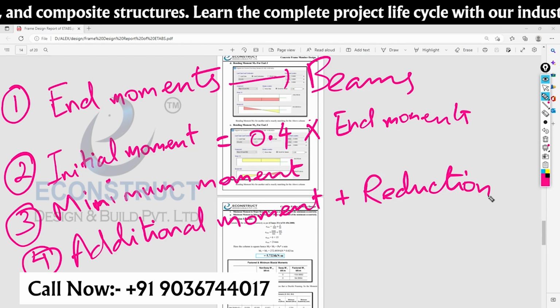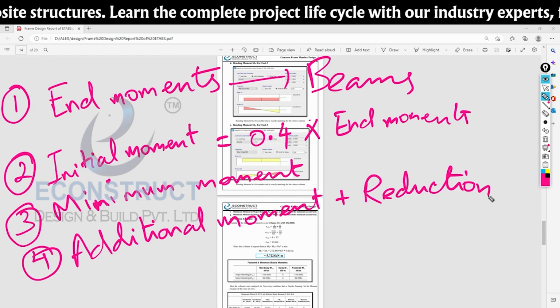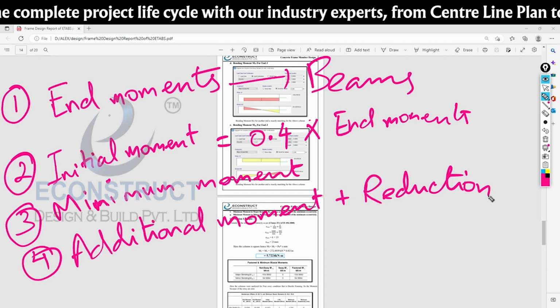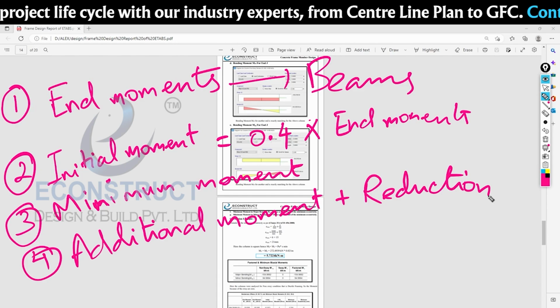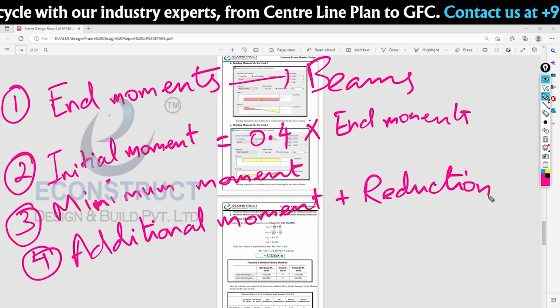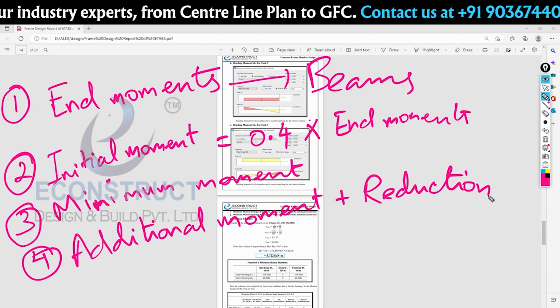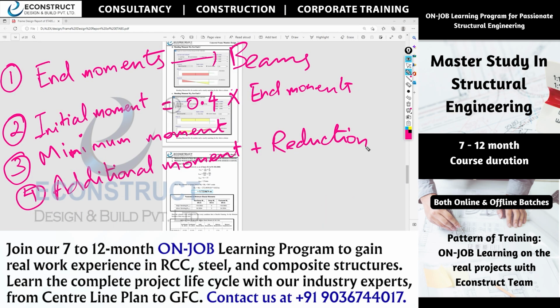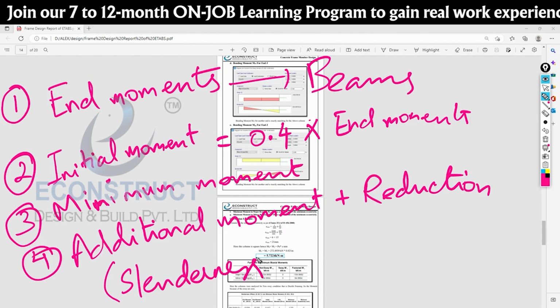Out of these 4 types, whichever moment is critical, you will take and design for it. The software will automatically design. Any doubt in these 4? No need to go in depth about this. You just need to understand there are things like initial moment, minimum moment, additional moment. Additional moment happens because of the column and is generated based upon your slenderness effect.